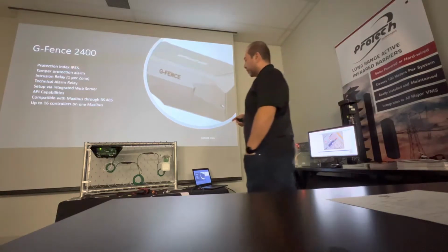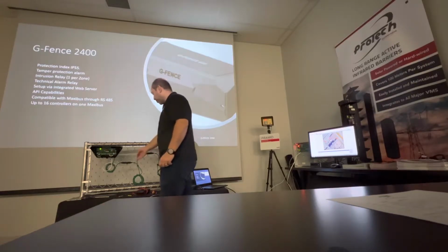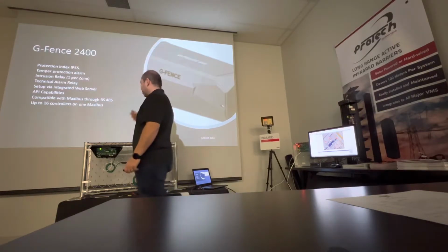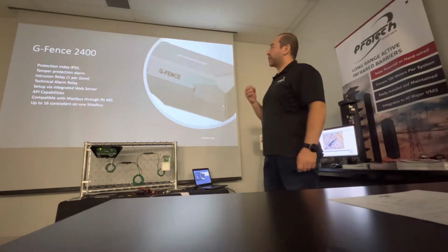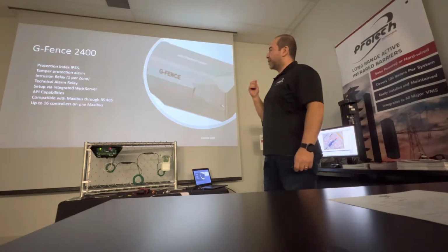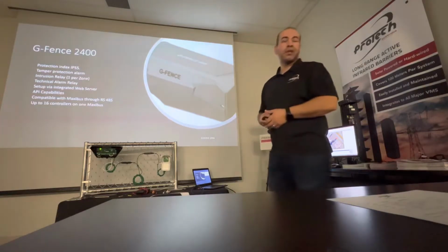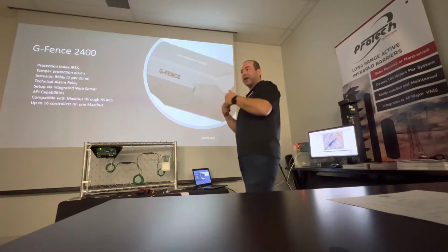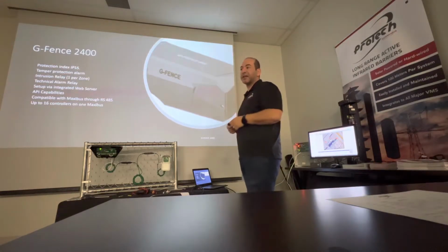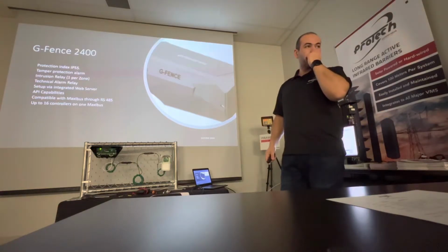Technical alarm relay. So what does technical alarm relay mean? If someone cuts the cable here, or cuts the cable here, wherever along the perimeter, it will generate a technical alarm. The maximum response time for the technical alarm is by default 30 seconds. So after 30 seconds, you will receive the technical alarm. But when you put back, let's say you splice together and put back the wire, it will be less than 10 seconds. Does that identify the nearest device that it's on?